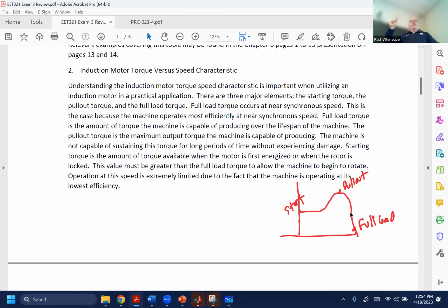You can put devices that will prevent the unit from operating because the temperature is too high. Small motors, you do that. Large motors, they use things called thermal overloads, which are usually much tighter in tolerance and usually are adjustable, especially the ones today, which are all microprocessor based. You can get them to be exact if you want. But if you're less than 5% over full load rating, you may want to rethink the application.